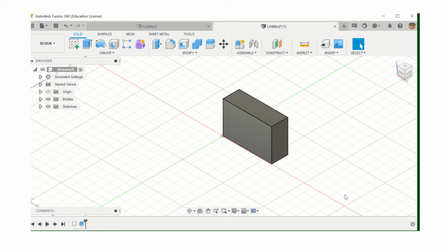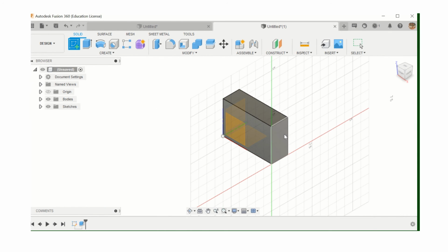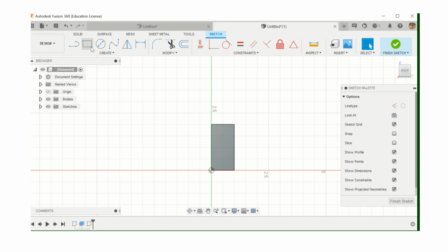So to do a subtractive method now, I am going to cut away the section that I don't want. And I can cut it 2 ways. I can either cut it down from the top or in from the right-hand side. Either way is fine. So I guess we'll cut it in from the right-hand side, but it doesn't matter. So we're going to start a new sketch. And again, notice it doesn't automatically know where I'm going to start it. I'm going to start it on that surface, and it will flip it like so.